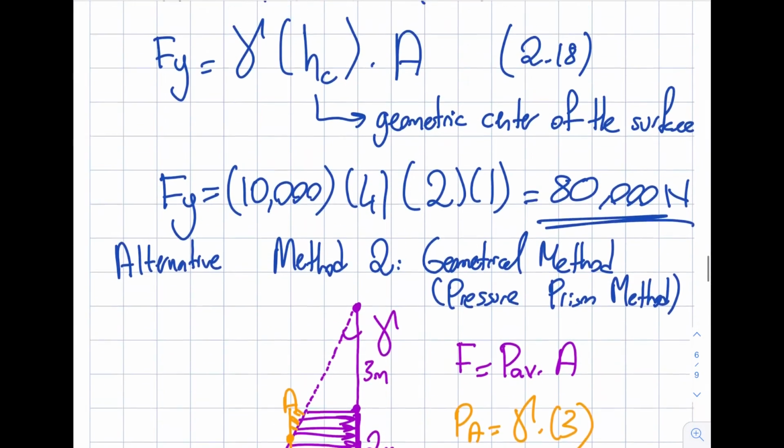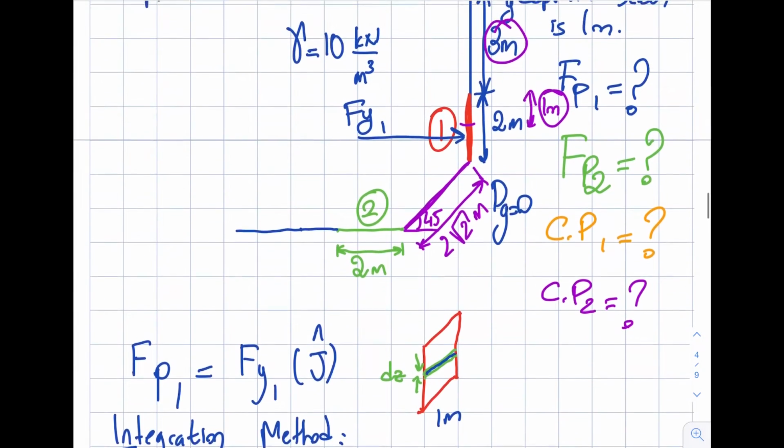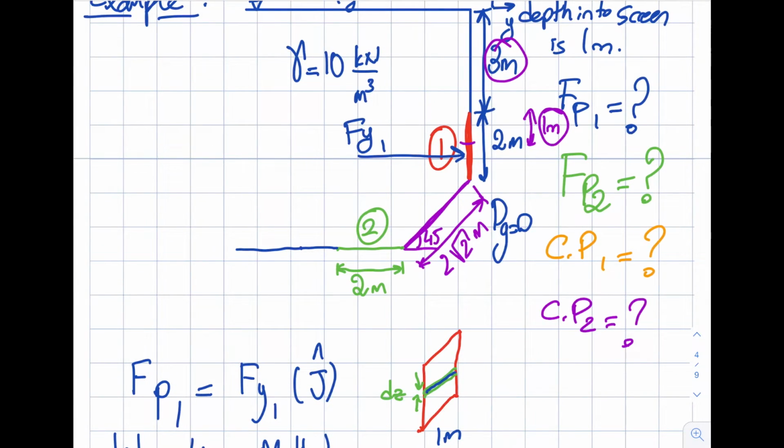As you see here, we discussed this when I was talking about the center of pressure. You can see that it is not here, and this distance that I obtained is fairly small, right? So this distance is 0.083. So it's a little bit lower than the center of pressure. This is important for the FE exam. If you don't have time, you can eliminate some of the options by knowing where the force is acting. It will be a little bit further down, so you can make some educated guesses if you're running out of time in the FE exam.